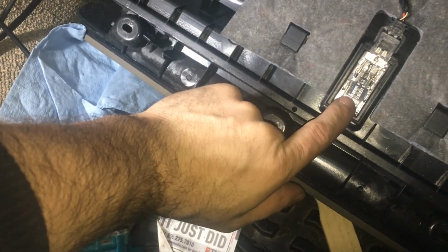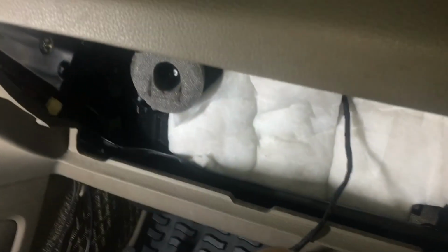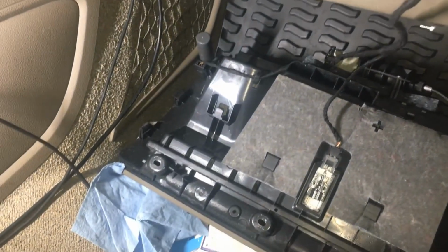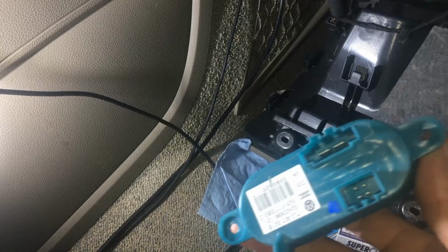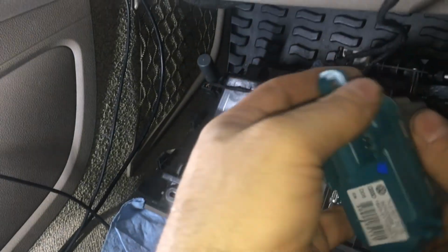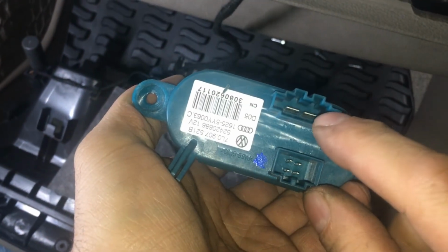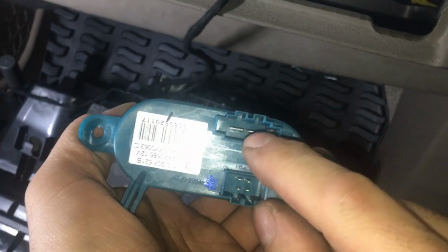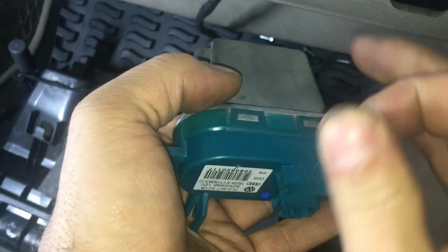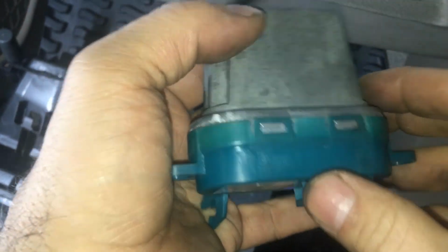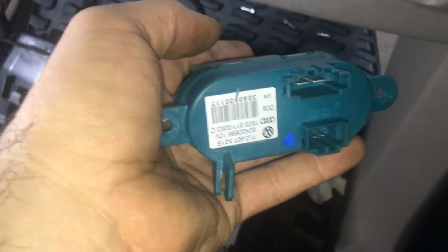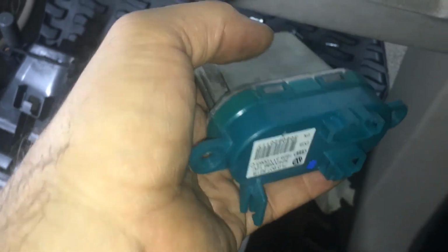And there's my lovely LED conversion light. Definitely get LEDs for the interior of this car. They're so much brighter. And then I'm going to do a separate video taking this apart. I know on my Crown Vic, because these things draw so much current, that's a whole different situation. Well, actually, it could be the same thing. These heavy leads that carry a lot of current, on the Crown Vic on the circuit board, they desoldered, and all I had to do was just resolder them, and we were good. Actually, you know what? I'm going to go do that right now, because if that's all that's wrong with the factory one, I'd rather have the factory one in here.